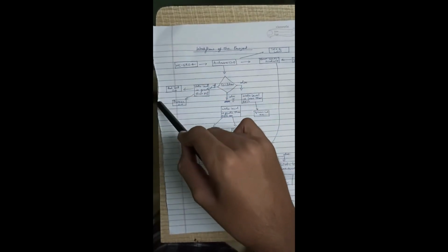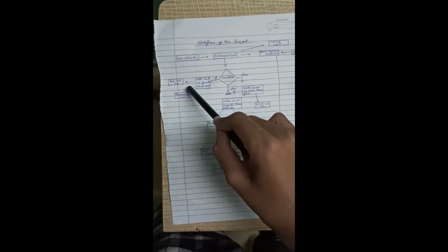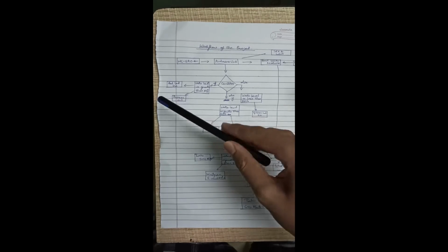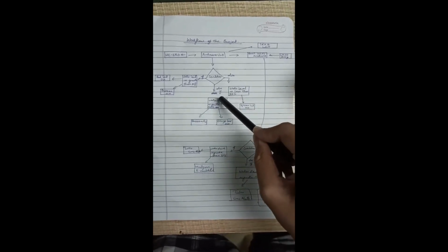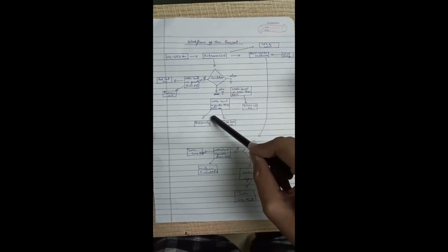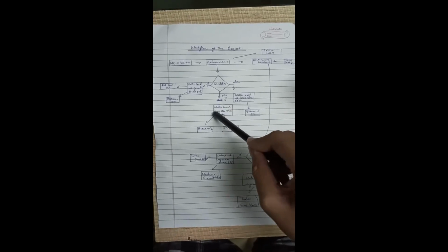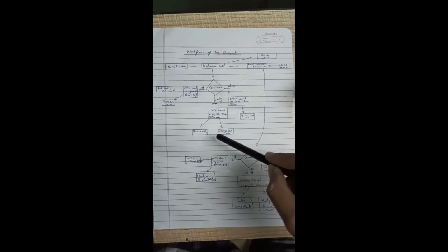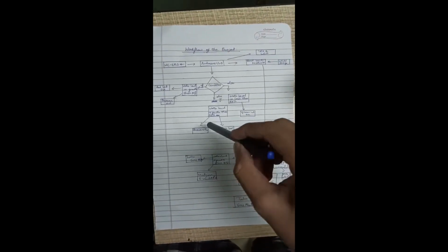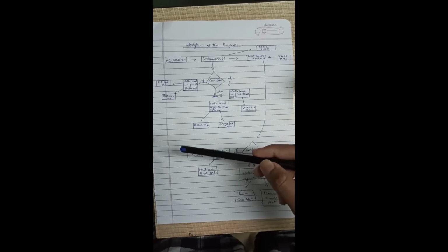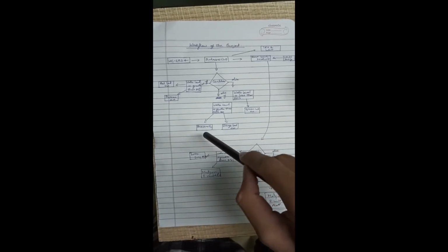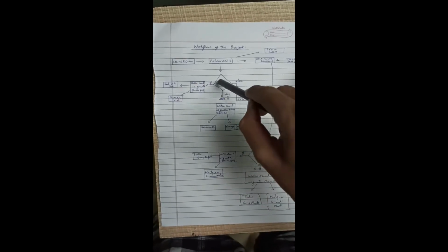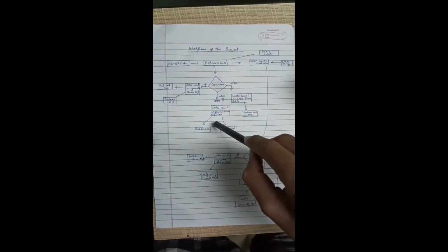Now this resembles that the water level is in the red alert, which means the water level is more than the max level. And in the else if condition, the condition is if the water level is greater than 55% but less than 80%, the Arduino code will give the command for the buzzer to buzz and the orange LED to be on, which means the water level is in the orange alert.